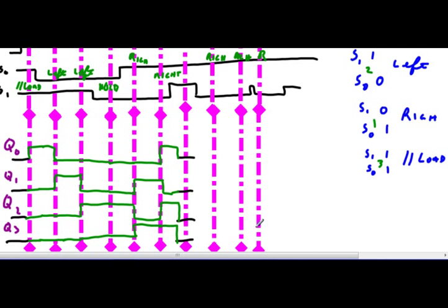Then I do another right, which means I bring in a 1 from here. The 0s get shifted. I do another right. Another 1 comes in, that 1 shifts, and the 0s stay the same. I get another right, a 1 comes in, and the 1s go up. I have a 0 there. One more right shift: I'm high, I'm high, I'm high, and that guy goes high. Ta-da! All done for 1 lousy point on the next test.